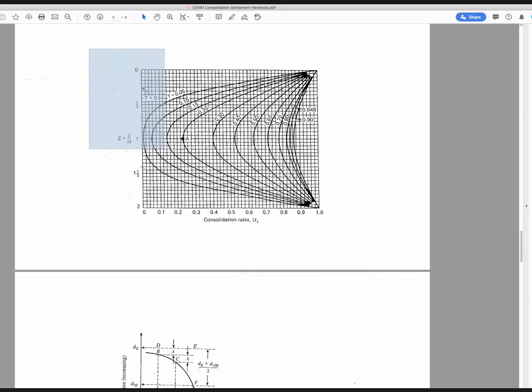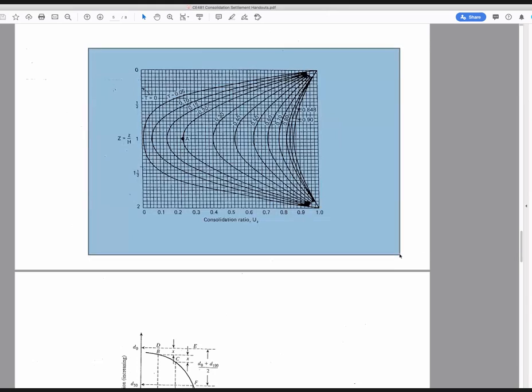This is a graphic of the collapsing excess pore pressure with time. As a layer of compressible soil is loaded, it would gain pore pressure and actually hold that entire load, and then, as is shown here, would dissipate towards the drainage layer shown on both top and bottom.